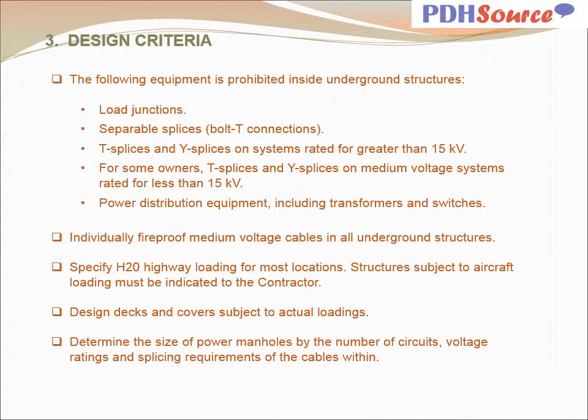Specify H20 highway loading for most locations. Structures subject to aircraft loading must be indicated to the contractor. Design decks and covers subject to actual loadings. Determine the size of power manholes by the number of circuits, voltage ratings, and splicing requirements of the cables within.